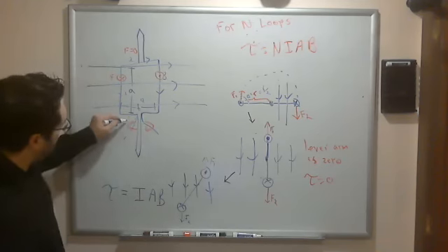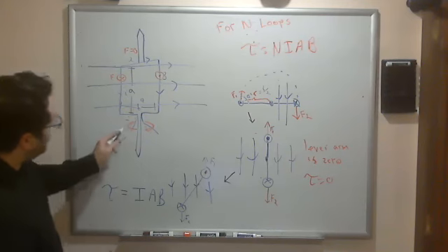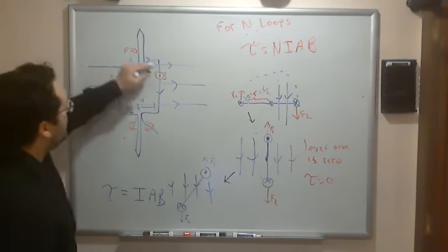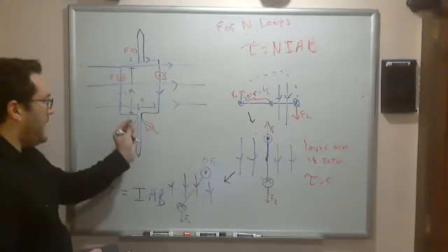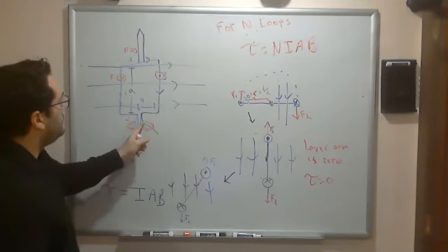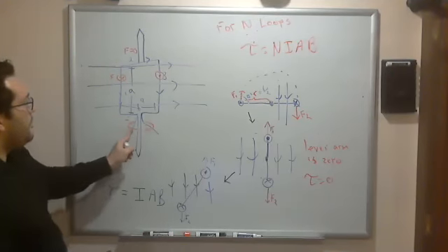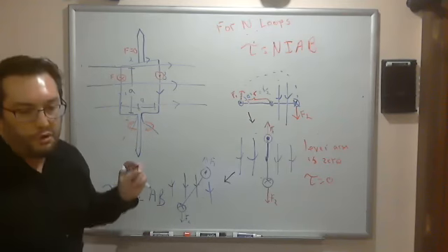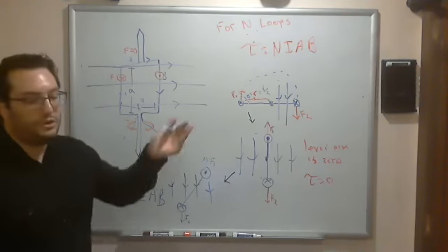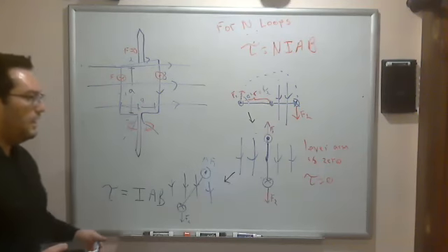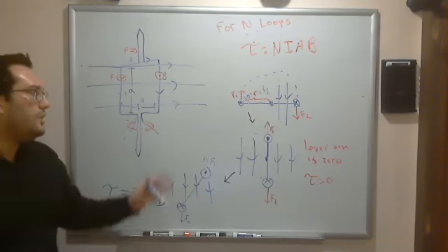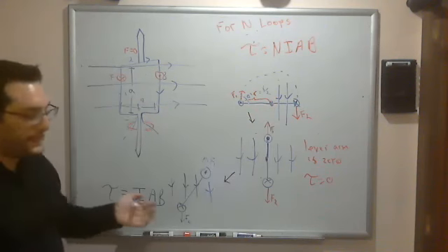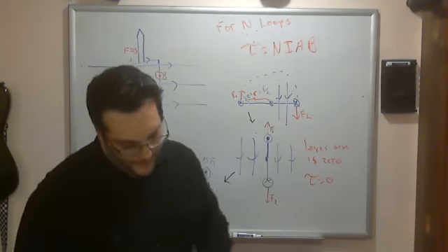So that if this is positive and negative, as this is rotating on this side, the current will go accordingly like this. And then once it rotates fully around, this side will now be over here, and then the current will reverse itself, and then you'll get torque along the same direction, no matter where this loop is. Right?